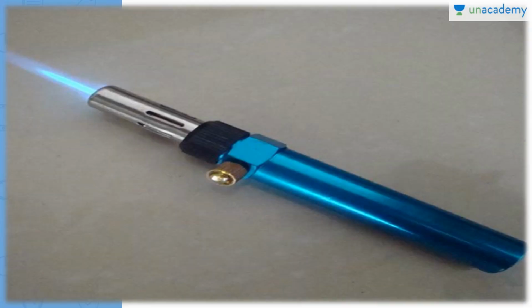So this is actually the torch method. So what is the torch method? Torch soldering utilizes the heat of a flame, you can see here, which is issued from an oxy-fuel gas torch. The torch mixes a fuel gas, like acetylene, and oxygen in suitable proportion, and it burns the mixture at its tip. The flame generated at the torch tip is directed at the workpiece with a flux applied on their surfaces. When the workpieces are heated to a suitable temperature, the solder is fed into the joint region to melt and to flow into the gap between the two workpieces. The solder also cools down and solidifies, forming a joint.